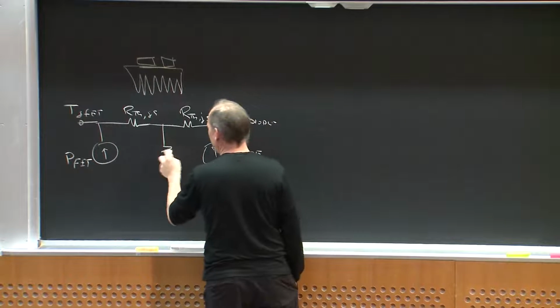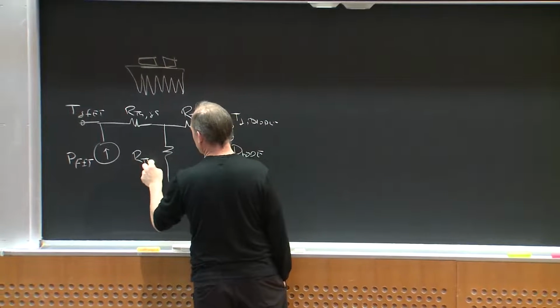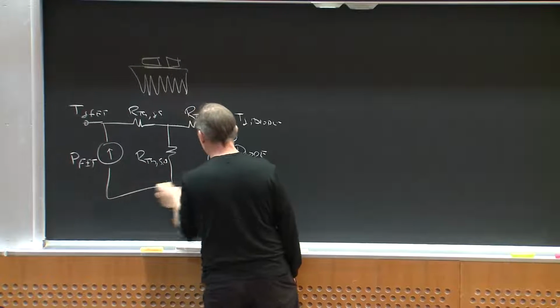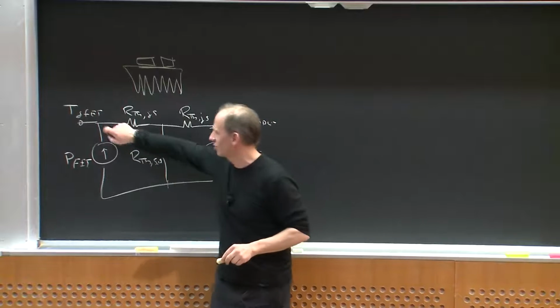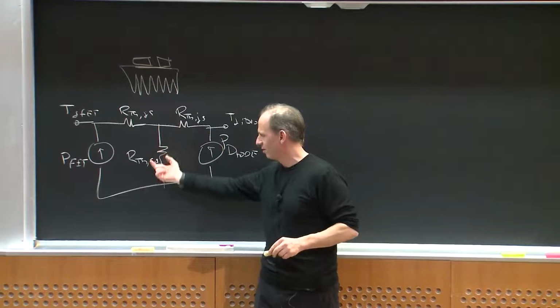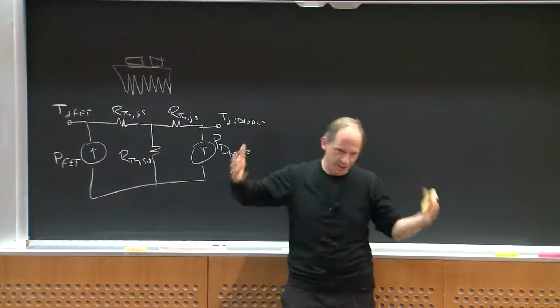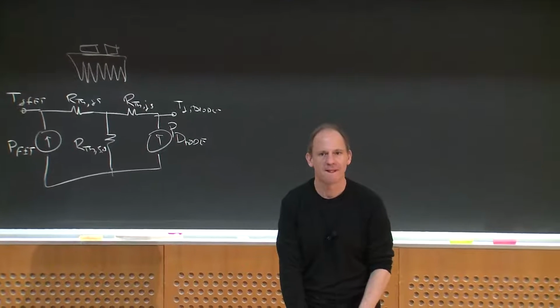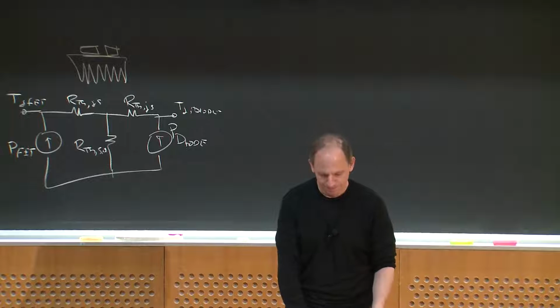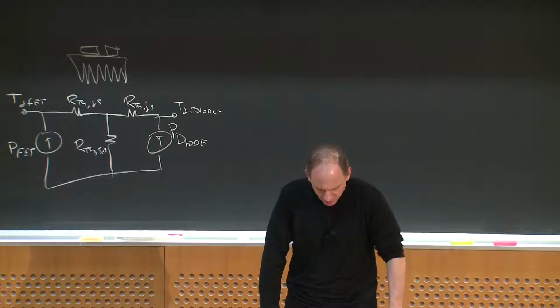Right, and then you go out and get one RTH sink to ambient, and you'd go calculate what the junction temperature of the diode is and what the junction temperature of the FET is, and you'd have to pick these things low enough. And you can expand out from there. Questions? Okay. So that's one way to think about it.